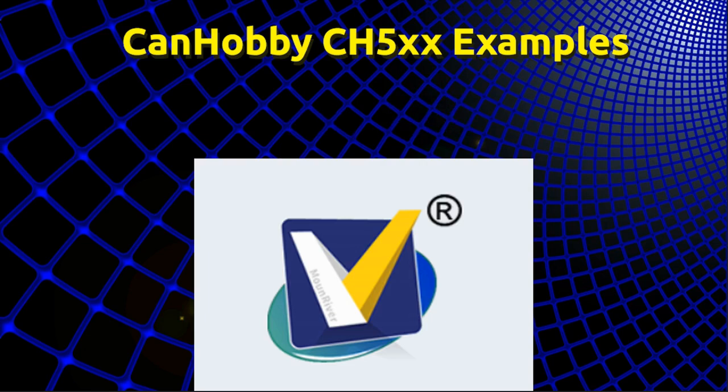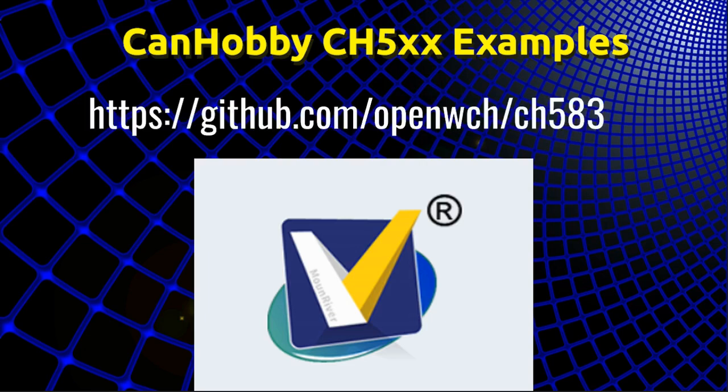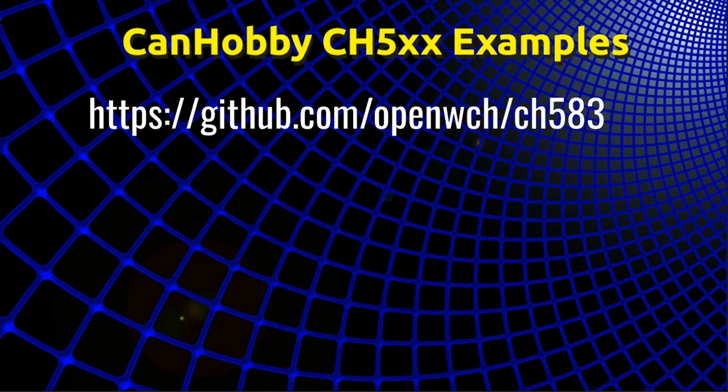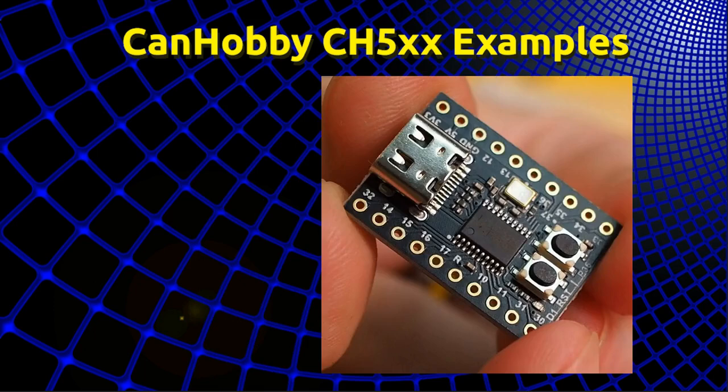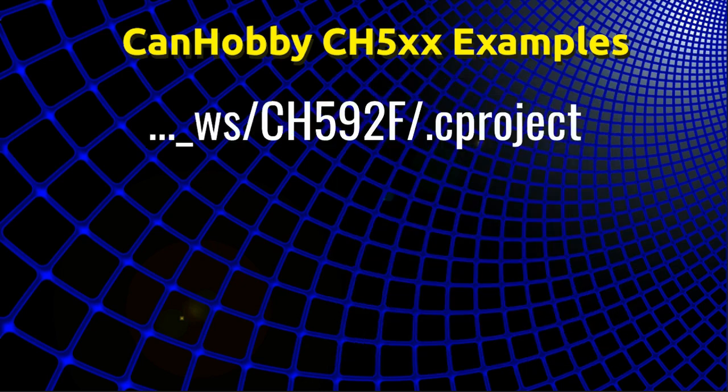I also came across some anomalies in the example programs given on the WCH GitHub. For an unknown reason, the individual examples given tend to exclude some references to the libraries for other peripherals. This can easily be solved by editing the .c project file.